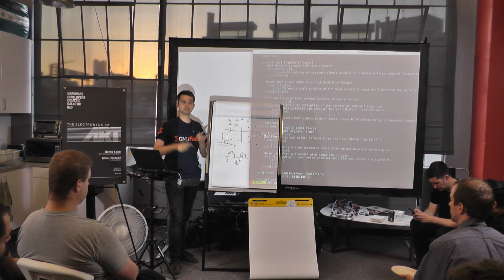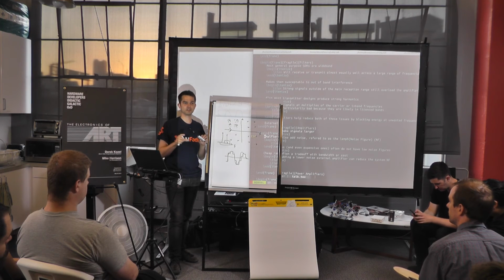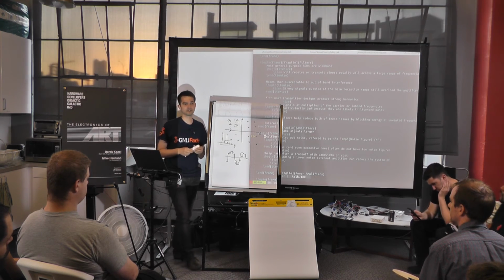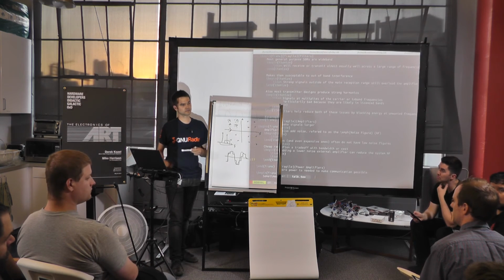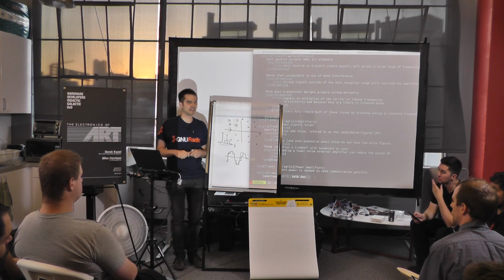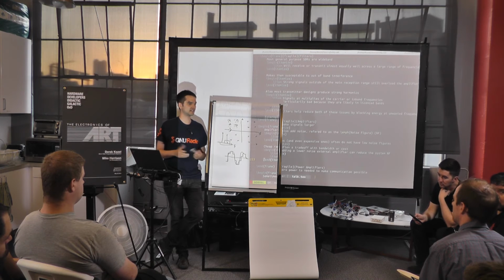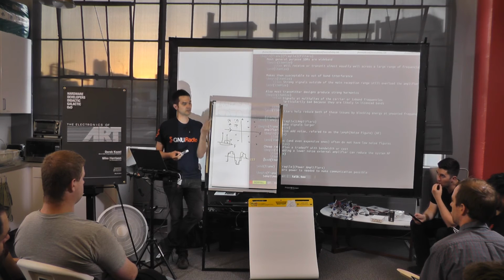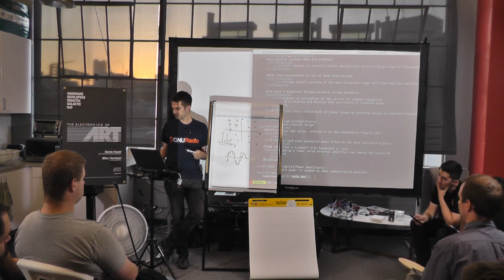At Maker Faire, we were still getting 30, 40 miles of reception with one of these without an amplifier, but with a filter. And then with an amplifier at home, I get about 150 miles of range. What frequency is the airplane data? The airplane data, ADS-B, is at 1090 megahertz, which these will easily cover. So this one works from 24 megahertz to 1.7 gigahertz. This one here is 70 megahertz to 6 gigahertz.